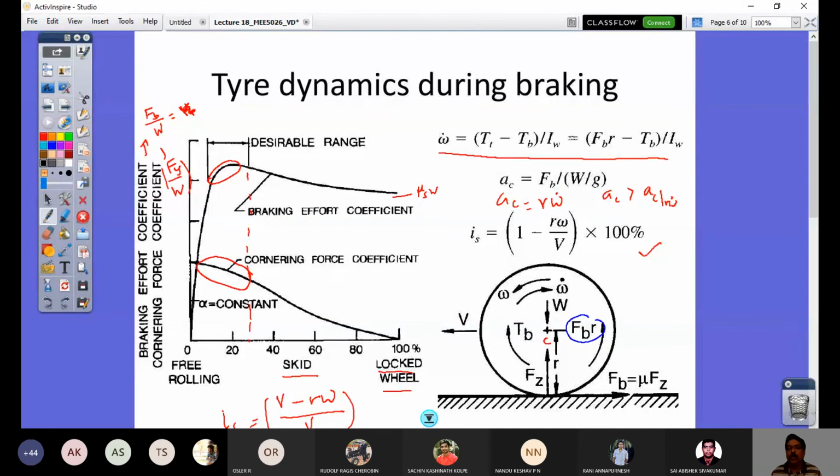So good morning. We were just looking at, in the last period, this screen which is shared here. What is the necessary dynamic understanding of your tire during braking? That's what we have seen in the last period, in order to ensure preventing locking of wheels. So this requirement of your free body diagram can be achieved through an advanced electronic feedback control system, which is employed in all vehicles mandatorily today, what is called an ABS, anti-lock brake system.